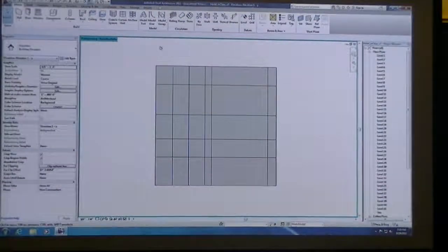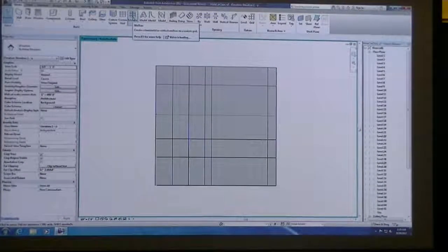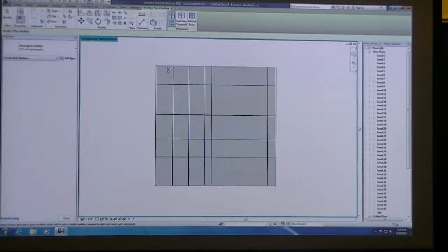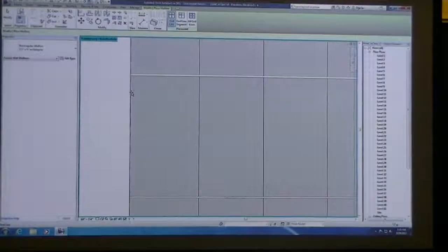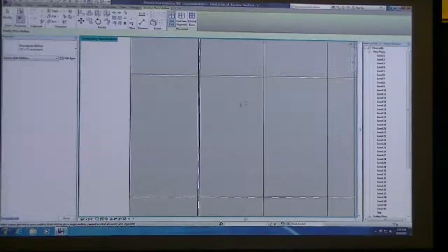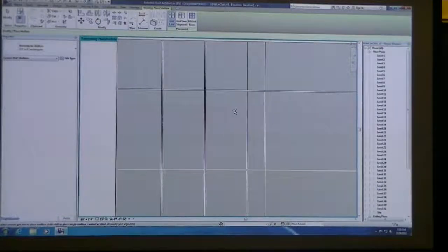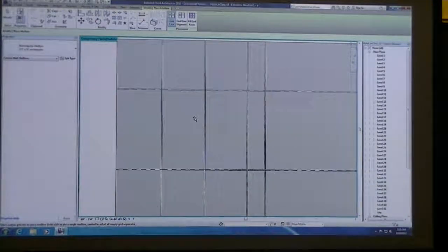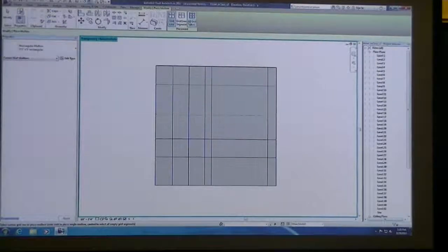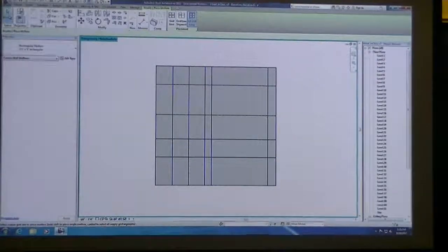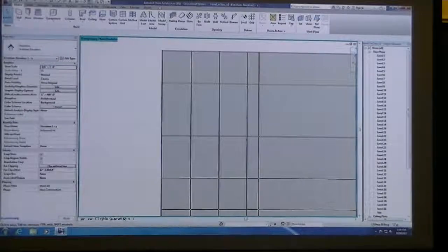And when you're done dividing it up into little pieces, just click under Mullion, and you can add a mullion at each grid line one at a time. So I can click on it, and notice that I get this white line now because I'm actually adding a mullion and breaking this up to be something more real. Or you could save yourself some time and just click on All Grid Lines and hover over, and there you go, you've created mullions everywhere.